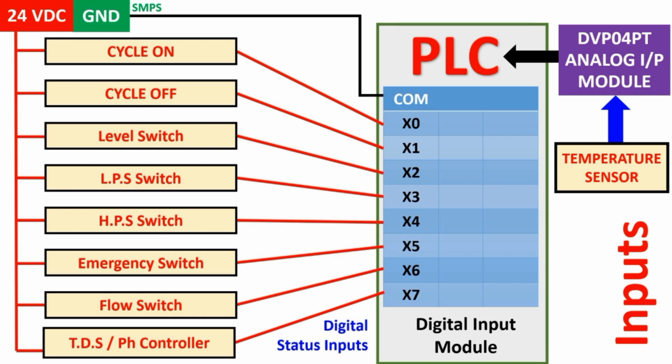Also in the industrial RO water system, there is a low pressure switch and a high pressure switch. Again, this is also NO/NC context, how it is used and why it is used. Let me tell you. So low pressure switches are generally connected in NO terminal, meaning when the desired pressure is achieved, then only the system should work.